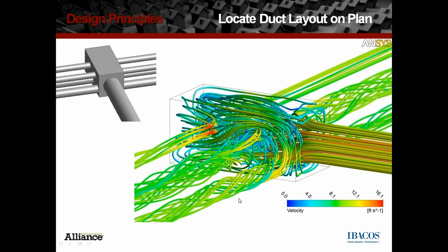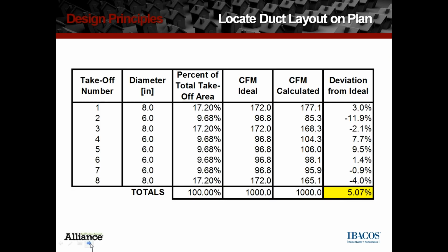Arn, from this picture, there's a lot of swirly lines here, but which of the supply branches have the best airflow? The far two outlet ones. And I'm sorry, I don't have a number to line up at the table, but you'll see that in the numeric table. It's the straight line flows. Yes. Less energy lost in swirling around inside the ductwork.